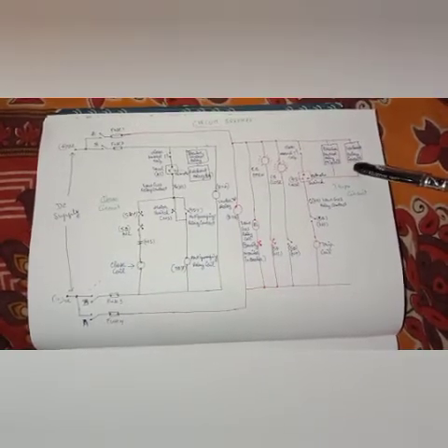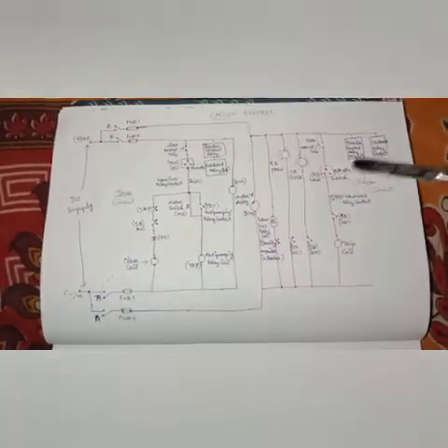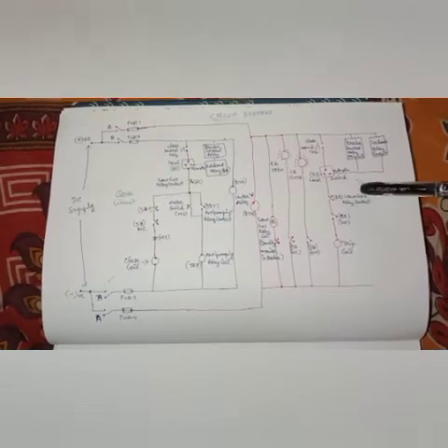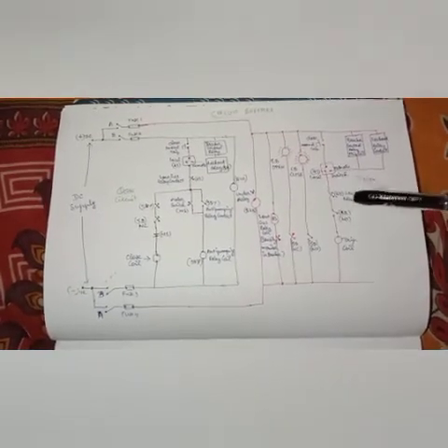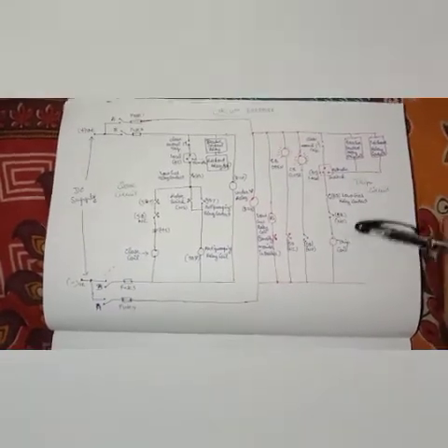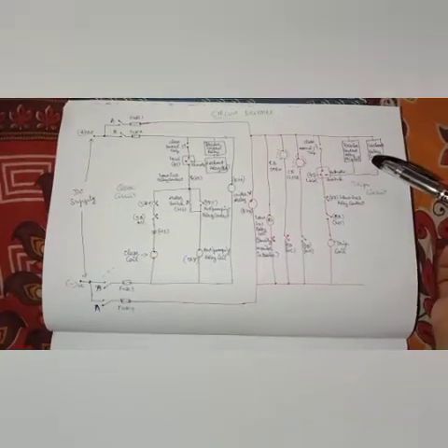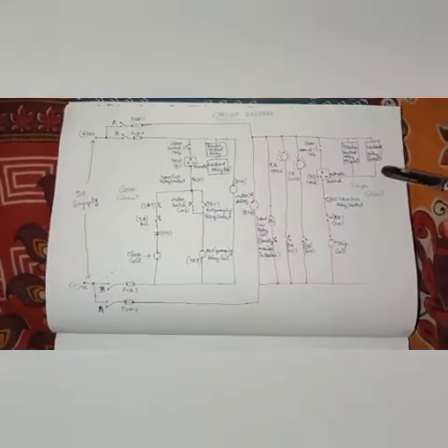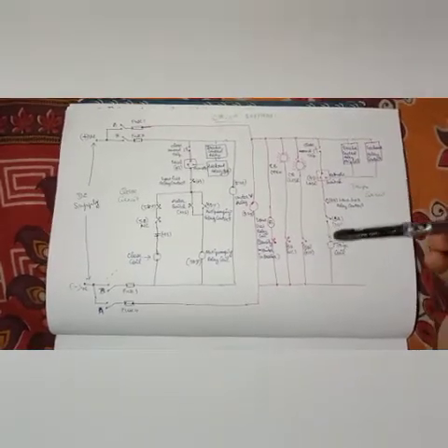Then the lockout relay checks the condition of your breaker, and also verifies with the other protective relays, which means whenever any fault is occurring, the protective relay will operate, and it initiates the trip to the tripping coils of your breaker.